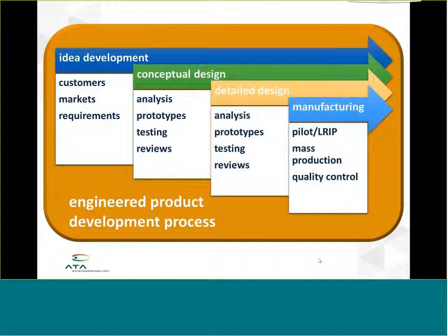PMI can also be used to speed development upstream of final product definition and manufacturing. It can be used to capture and archive design decisions and intent and eliminate many extra steps in the documentation, communication, and review cycle. For highly engineered products, the time and cost spent in design and development stages is substantial. PMI can be used to reduce mistakes, miscommunications, and rework, particularly across large teams or multiple organizations.